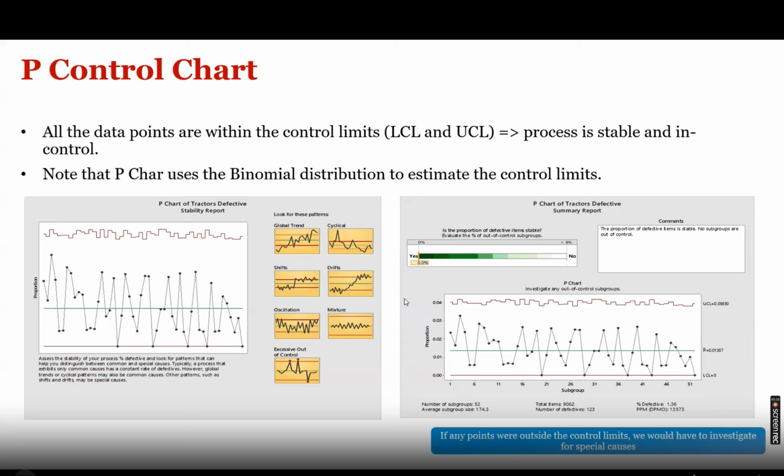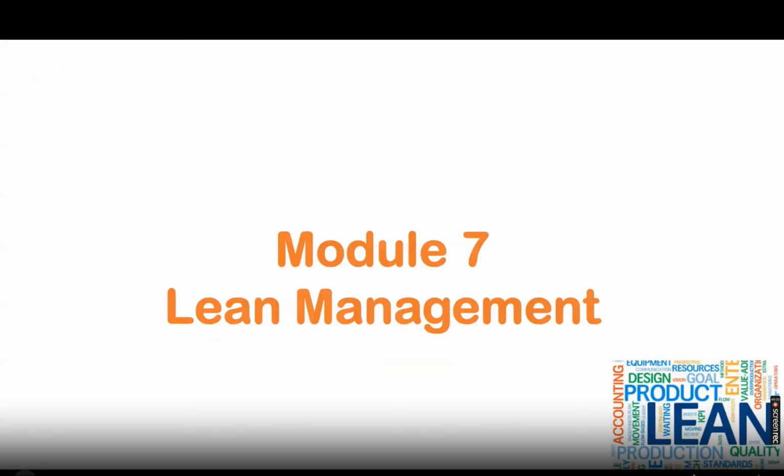As I said, for continuous data, when there are no subgroups mentioned, as we did with that IMR chart, we will do an IMR chart. If the subgroup sizes, or the number of times the measurements are taken, are less than 8 specifically mentioned, we will do an X bar R chart. And when the subgroup sizes are more than 8, we do an X bar S chart.